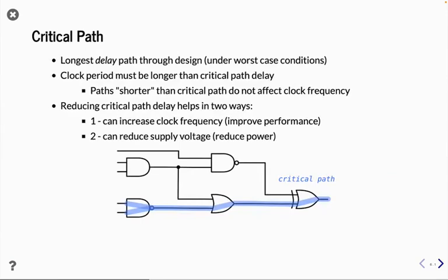Cool. Okay, so why are we so concerned with delay? Well, your delay is going to set how fast the circuit operates, right? We talked about how in synchronous digital systems, of course, we use a clock to synchronize everything. So everything goes to the same beat, the same clock, to do state transitions. And well, how fast can that clock run? Now, in 2023, one of the biggest limits for how fast a clock can run is the power, right? Otherwise, it's too fast and runs too much power.